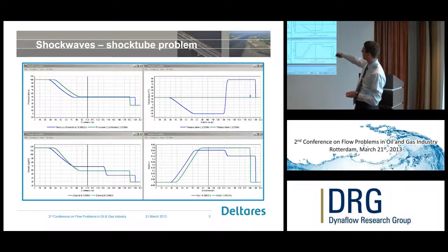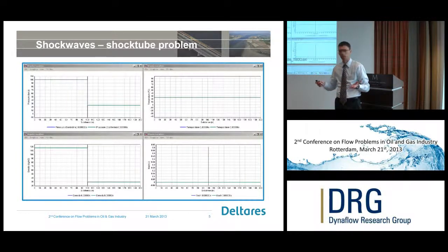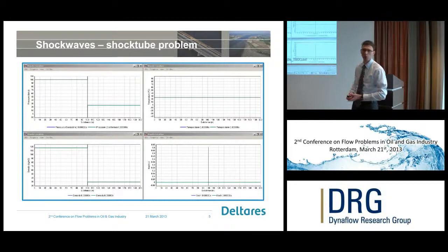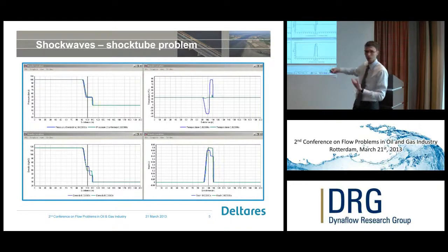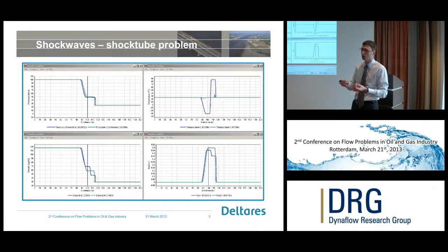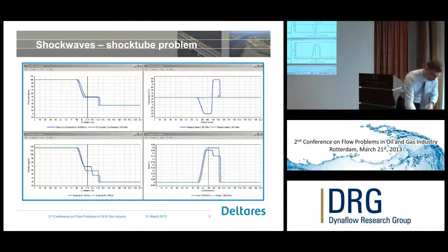The good thing is that the maximum pressure still gives you a good measure of what happens in reality. So with isothermal behavior, you still may get sufficiently good answers with respect to maximum pressures, but still I think that if you can include adiabatic behavior, or if you can include the insulation of your pipes, that makes the results closer to reality.